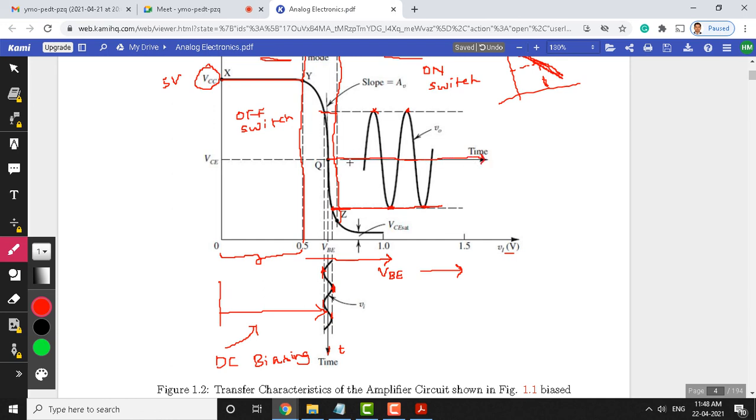Okay, you can see that here the signal is going downwards, and look at the output: when it is going downwards, here it goes upward, because the gain is negative. A negative signal becomes positive, because earlier we discussed the transfer function.